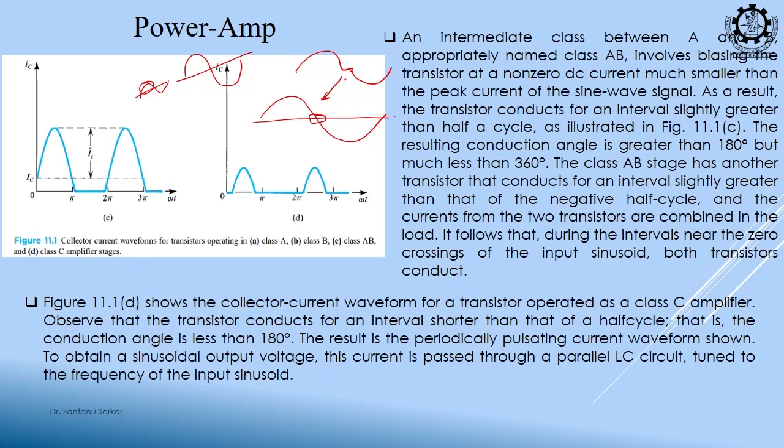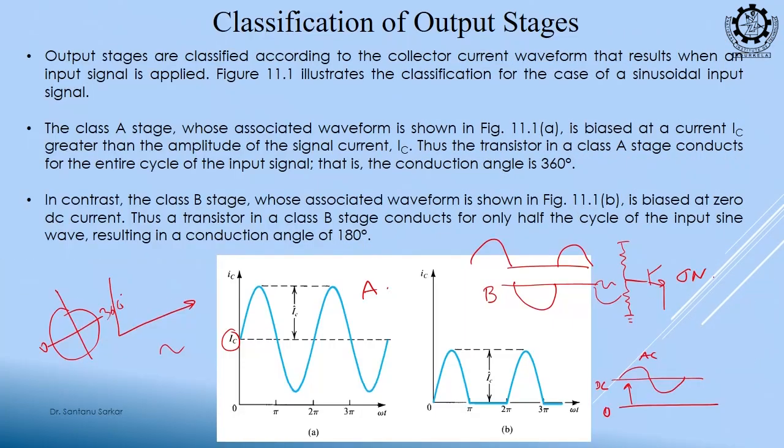It is not the exact replica of the original sine wave, or you can say that the THD, the harmonic distortion, will be more. And that is happening at which point? Zero crossing. So, this is zero crossover distortion. This was unwanted in which case?